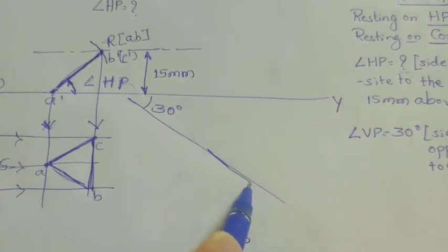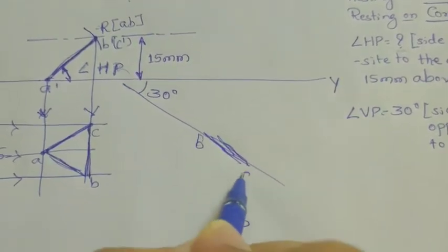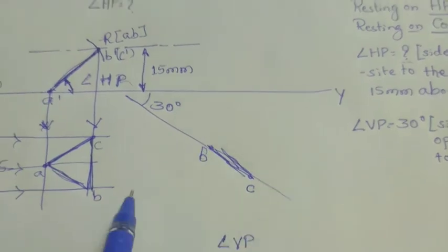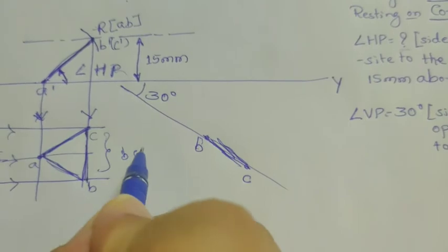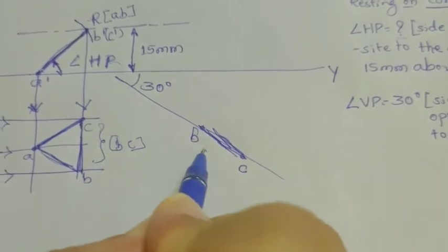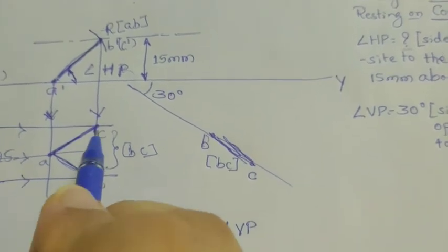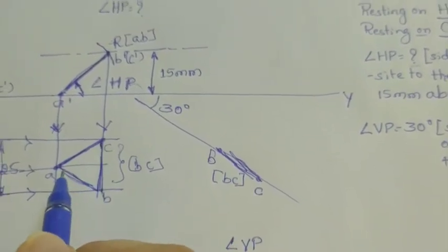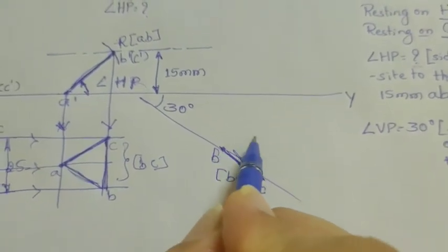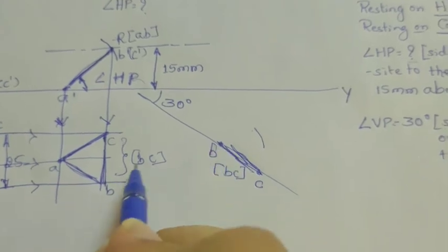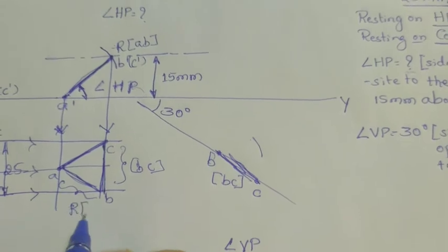So first initially we are going to draw BC line. Once it is done, which is equivalent to this BC dimension, then after that measure this C to A dimension and B to A dimension, then take B as center, draw one arc which is measuring RAB,